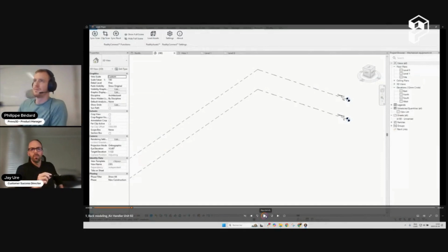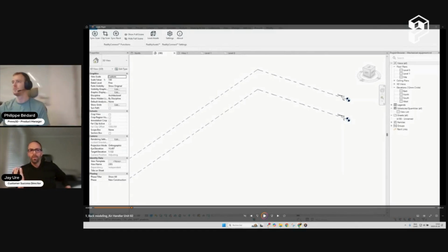Perfect. So the way that our Reality Plan desktop application connects with Revit is over port 3000. Open up Reality Plan, open up Revit, make sure your session is saved, and specifically if it's a new model. And then you will have the ability to bring in any assets that are already generated. You'll see in the different videos that we have a different listing in there, and that's just the amount of assets that have been generated in the layout that was available at the time in which we ingested the data. So the models have been fully coordinated.